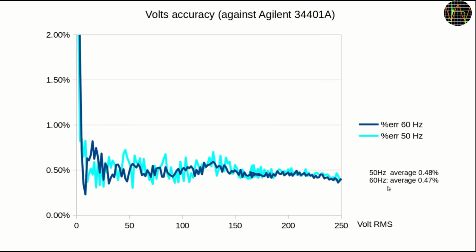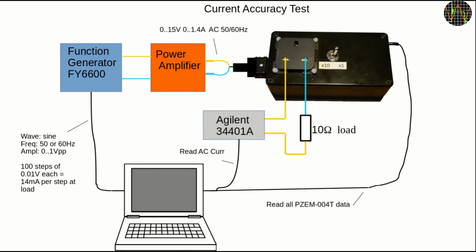Overall, I'm quite happy with the voltage accuracy of the PZEM-004T, which is true RMS, by the way. Of course, if you do the modification described in the first video, the accuracy of your module directly depends on how well you match the replacement R17A and R17B resistors to the original R17. But since my resistor pair matched to a difference of 100 ohms or so, the unmodified PZEM-004T should have the same 0.5% accuracy.